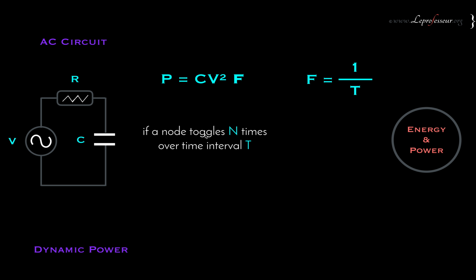This node came from the simple fact that the algorithms would be processing this whole netlist in terms of nodes and edges. Nodes will become the vertices in a graph, and edges will become simply the connections between nodes, and a net or a wire can be split into different pieces connected via nodes.